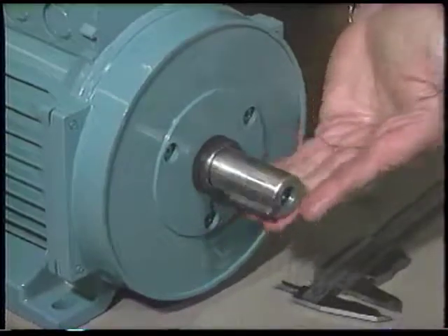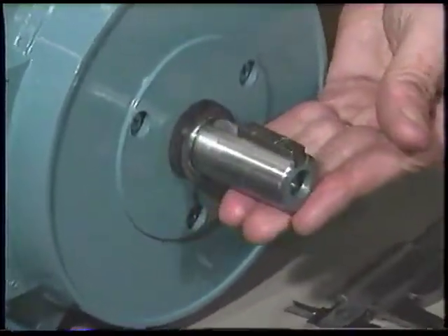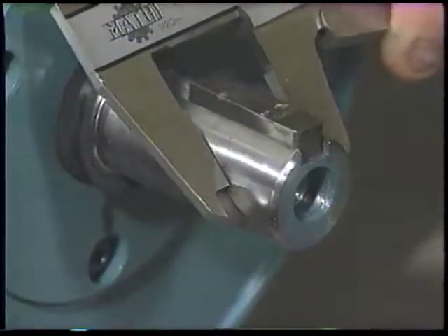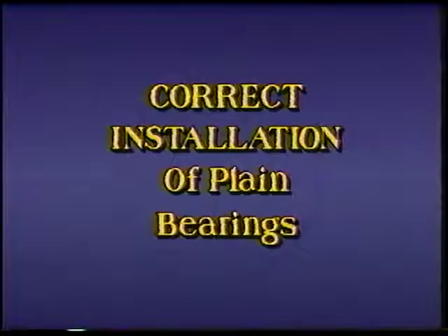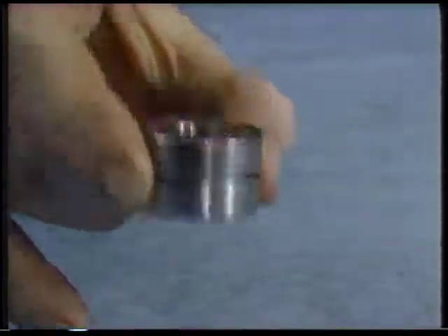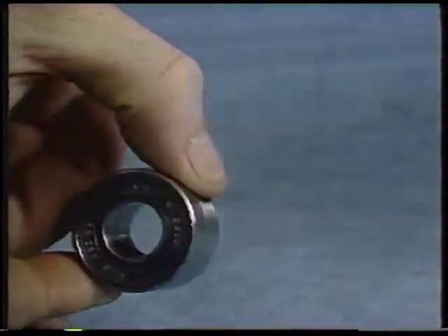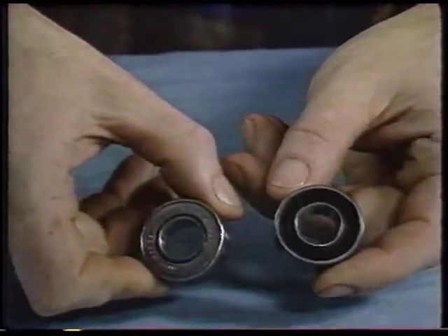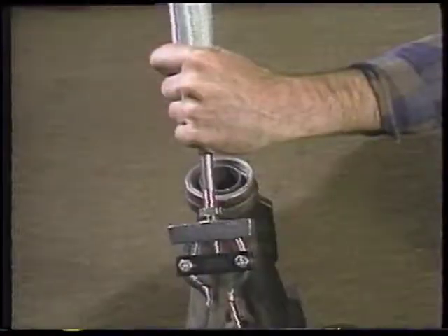Make sure the shaft is clean and free of defects. You must also make certain that the shaft and bearing diameters match correctly. If a bearing is to be pressed into place, it must fit tightly to ensure full surface contact. Any dirt or burrs or any damage to the bore or the shaft may prevent full contact between the bearing and the shaft.